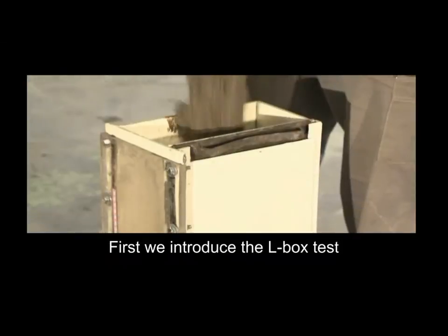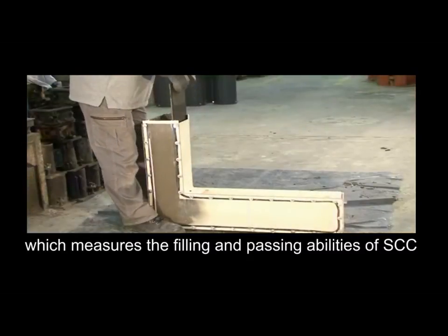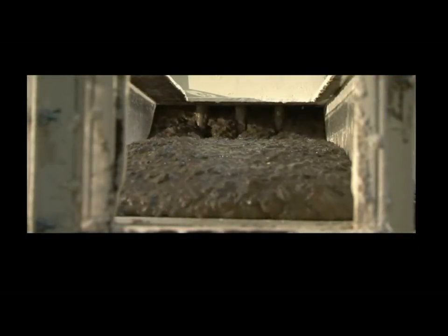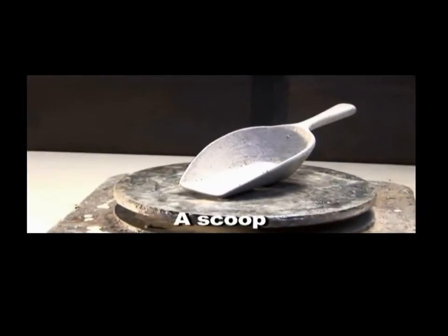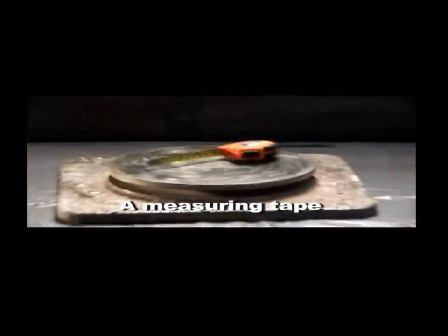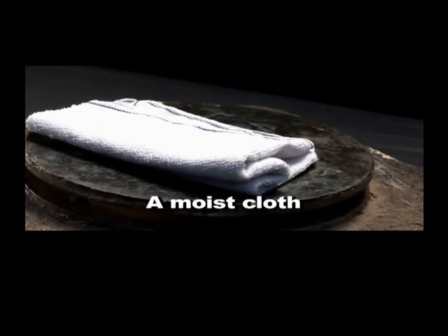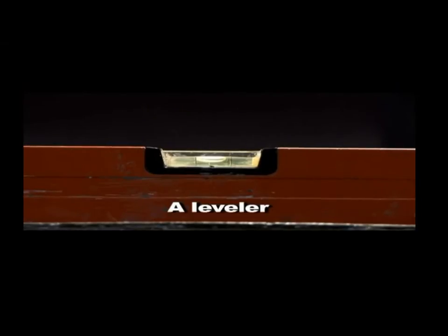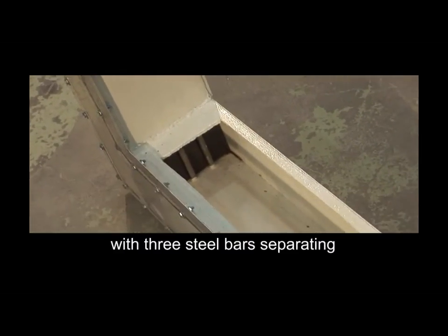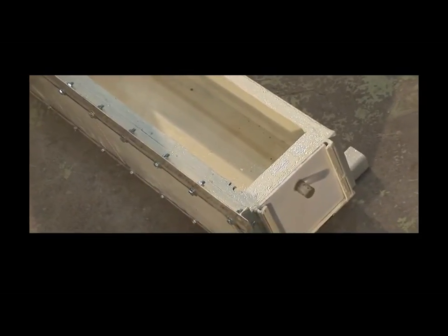First, we introduce the L-box test, which measures the filling and passing abilities of SCC. For conducting the L-box test, you will need a scoop, a stopwatch, a measuring tape, a shovel, a moist cloth, a leveler, and a L-shaped box with 3 steel bars separating the vertical and horizontal portion of the box.